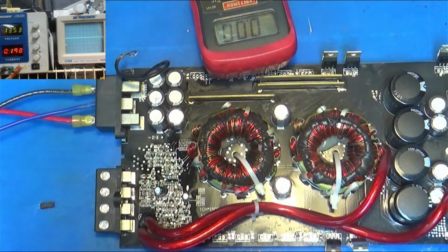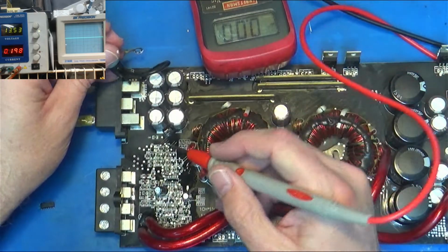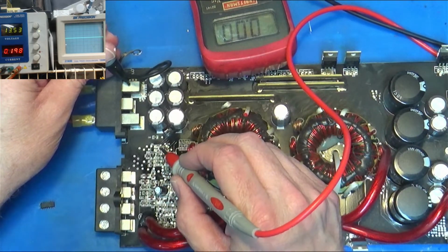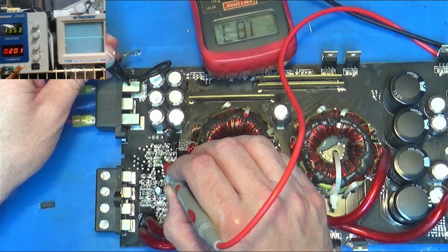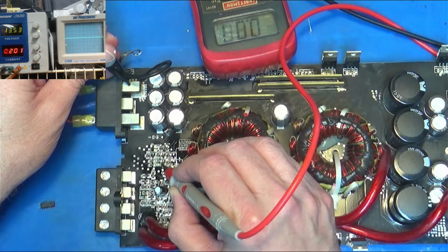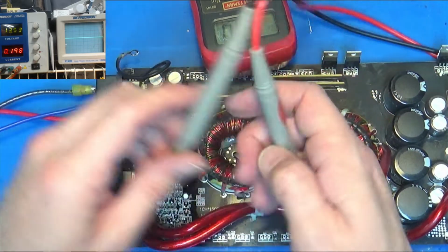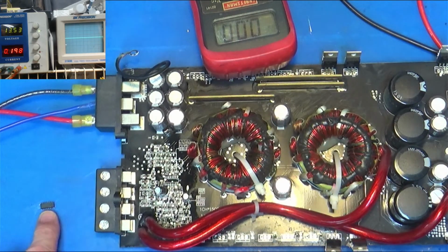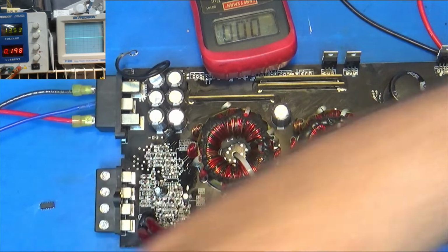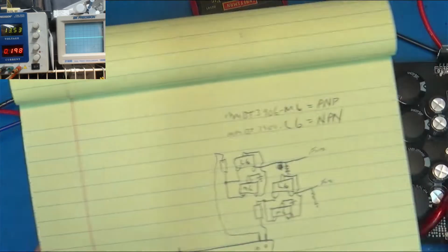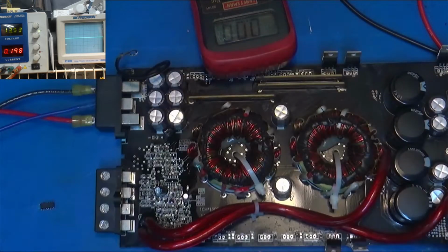So let's make sure their base was getting grounded, because those are PNPs. So this is what the base reads with no power on it. Then it gets pulled down, and so that should be way sufficient to turn that on. Both those. So I think those two need to be replaced. This chip may be good. So we know those are PNPs, and we're just going to go ahead and replace them with the MMBT3906s. Those will work.